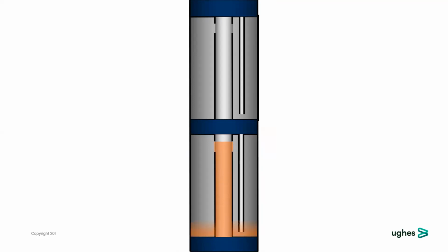The fluid goes from the bottom. This is the motor fluid, going all the way up, filling all the labyrinth chamber, and going through the connection between the bottom chamber and the upper chamber. And the dark fluid is the well fluid. You can see the dark fluid only has low volume in the bottom of the top chamber because of its higher gravity, so it goes to the bottom.